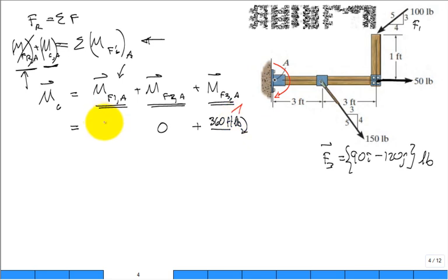All right, this last one is more challenging. What you would do, though, is you look at the point of application of this. Okay, let me back up. Some people may have said, well, where is this force applied? Is it applied at this point? And then maybe I've got to do an R, come out here with an R, and then an R cross F. Use the principle of transmissibility. Move the point of application of that force back to here. Then decompose it into components. Notice that F3 in the x, the line of action goes right through A, no moment. And only F3 in the y induces a moment with a moment arm of 3 foot.